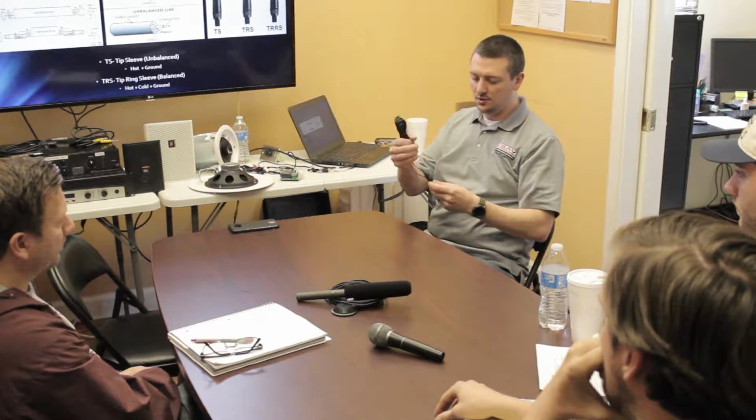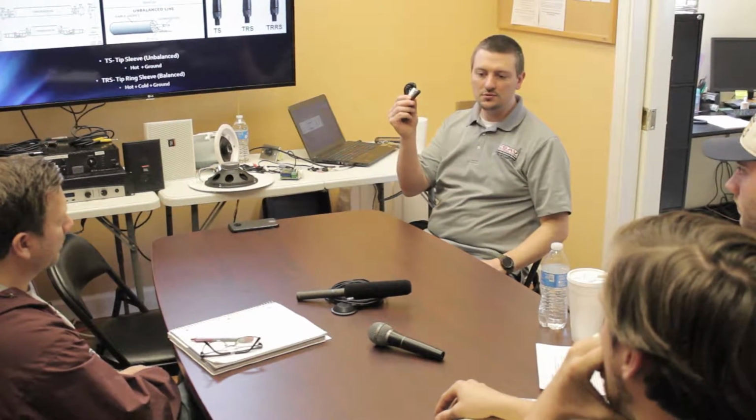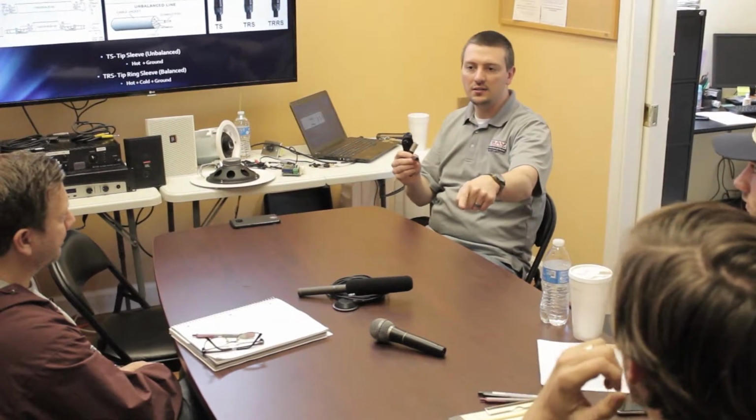But say this guy was hanging from the ceiling. With the same gain level that you would have driving this and that, you'd have to get up like here to get the same volume as if this was on the ceiling, as I'm talking right now, sitting 6 or 8 feet away from it. So, yeah, they're much more responsive. The condenser mic transient response is much quicker than dynamic. So the phantom power actually charges the element in the microphone.